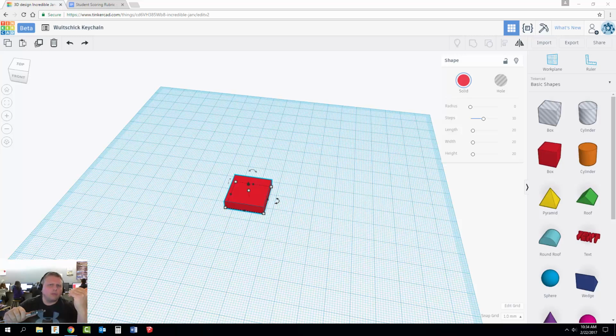If you're like me, I didn't know a whole lot about millimeters and metric measurements before I started doing 3D printing stuff. So look, what you're going to do is grab one of these digital calipers, and they're a really awesome tool. And what you do is you close them all the way, and then you press the 0 button. That tells it like, hey, right now it's at 0. Then you can move this knob and open it. For example, let's say that I wanted to see what 5 millimeters looks like in real life. You're just going to keep dialing this until it says, well, now it says 5.10, so it's about 5.